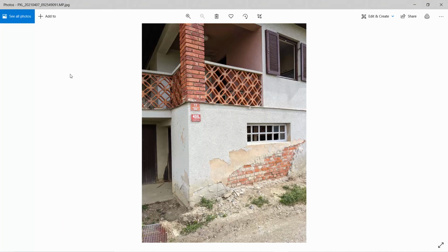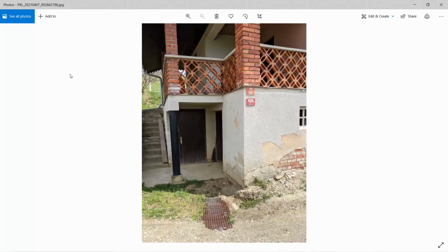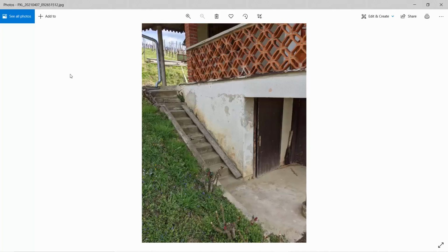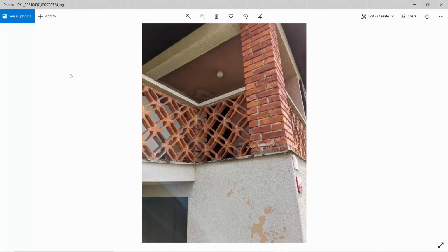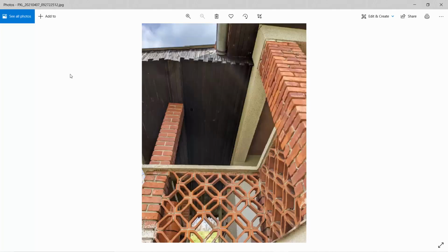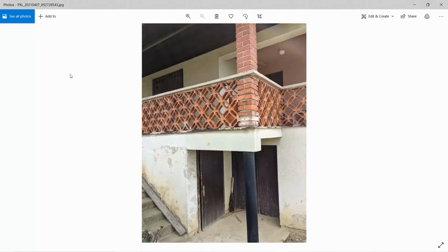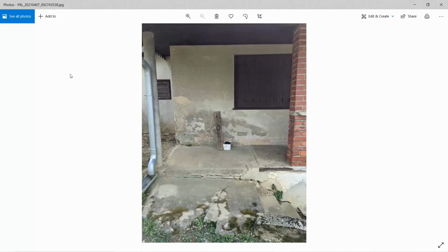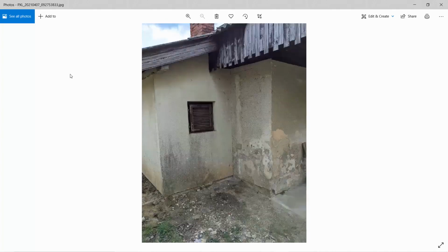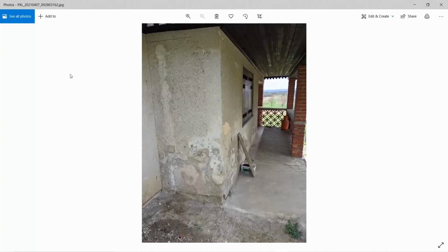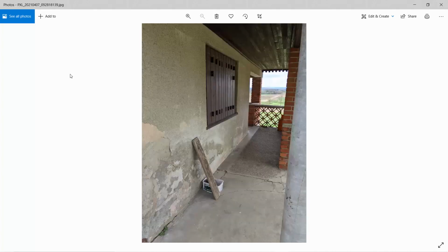You can see, when I trigger this image with the phone, it's almost the same as the drone image. And this is a good starting point. When these first 5 images are matched with the model of drone images, I can continue walking around the building, go even closer, go under the roof to get a lot of details, go around the building. Once the first part is successfully connected, those images will also be additionally connected and I can walk inside of the building.